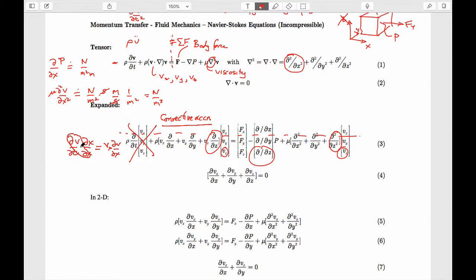And so if you take this derivative, which originally was dv/dt, you can write it as something that isn't changing with time, but is physically changing with space. That's exactly what you have here. These terms are all changing with space. So you take a snapshot at this point. If it changes its velocity from time 1 to time 2, then its velocity is changing. It's not steady state. But if it's steady state, so if you take a picture of the velocity profile at time 1 and again at time 2 and all the vectors look exactly the same, it doesn't mean that this term is 0.